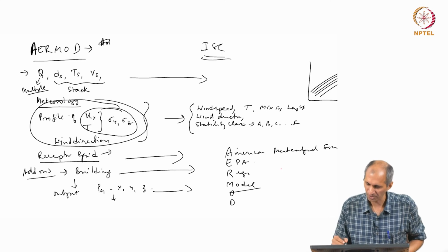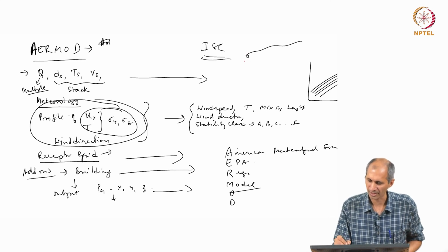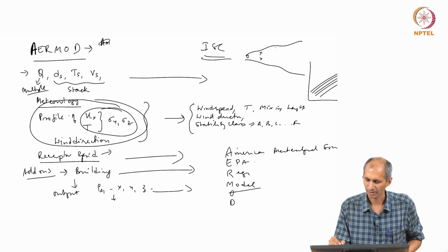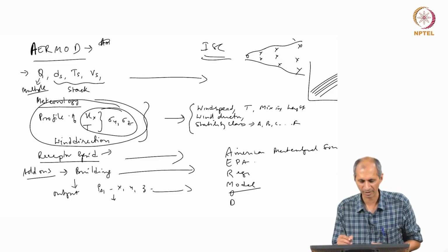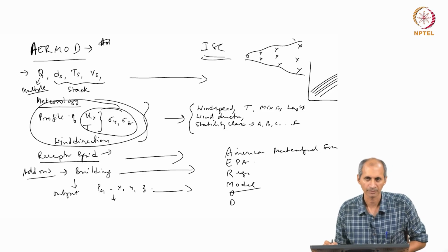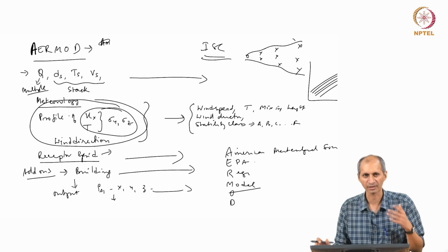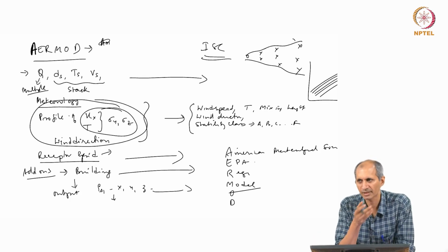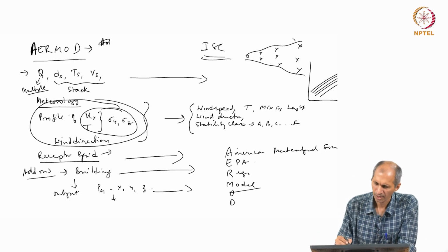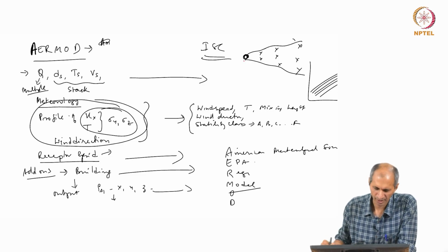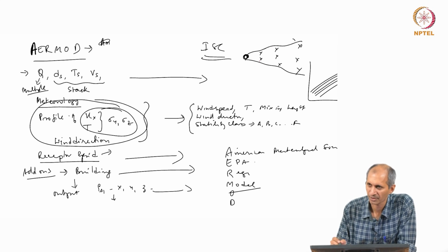Basically you release a certain chemical and predict concentrations at different locations. You also measure concentrations at those locations, and based on how closely it matches, you adjust the model. You have made some assumptions in the model, and you have to justify those assumptions or say that they are not valid under these conditions. A lot of experiments were conducted long back for verification of these models.